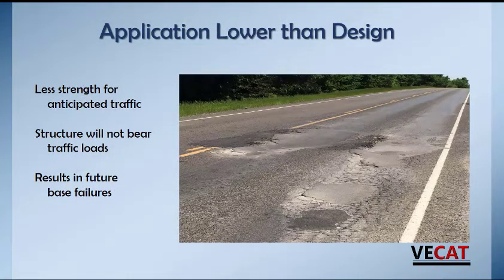On the other side, lower than design, you don't have the cement, so you don't have the load-bearing capacity that was designed into the mat. And as a result, it will not hold the traffic. You get rutting, potholing, and other problems. The biggest issue with both of these is you'll finish the road and you won't see any problems until a year or two down the road. Then all these items will show up as a problem.